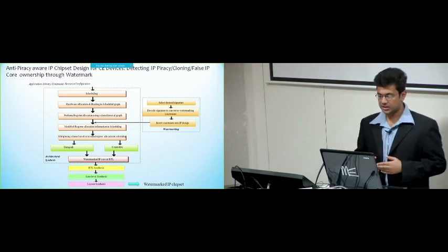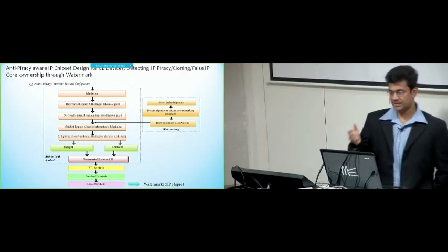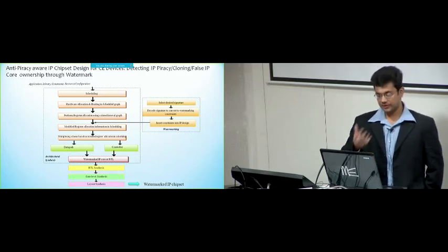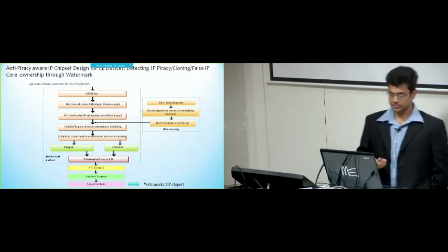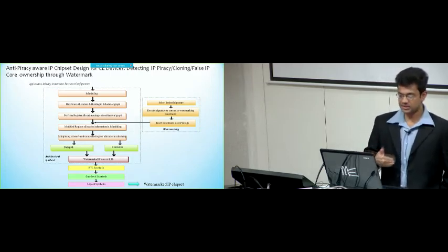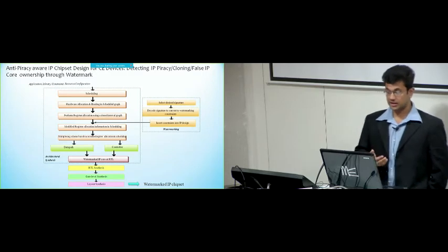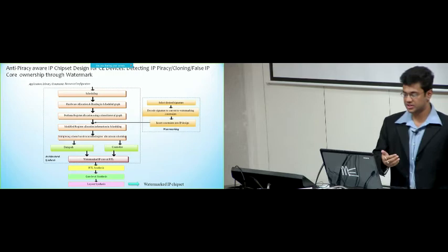In parallel, we can start selecting our desired signature that needs to be implanted onto the design, which is decoded and converted into respective watermarking constraints. These constraints are then fed into the register allocation design, where we finally get modified register allocation information in the scheduling. This entire process is then converted to a multiplexing scheme, which is used to find out the connectivity information in the data path and the controller, and these two together form the watermarked IP core at the register transfer level.